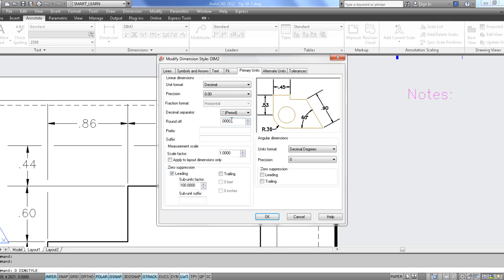Till what decimal you are going to round it up, those values will be rounded. So you can see 0.53 is visible here. If I am going for the values a single 0, here you can set the precisions. As per your precisions, these values will be rounded.